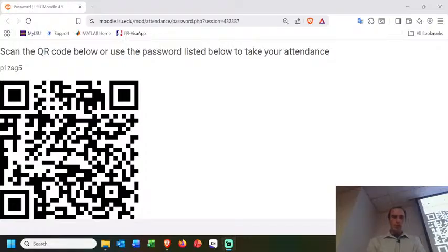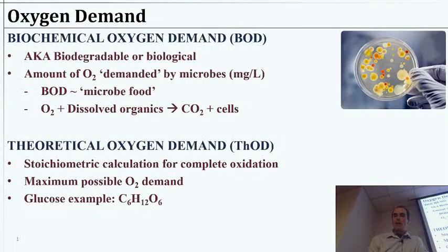And right now, today we're going to come back and talk about biological oxygen demand. So within the context of wastewater, we talked about this as kind of the primary conventional pollutant that we target because we don't want our rivers and waterways becoming anoxic because all the bacteria demand all the oxygen, right? We want to leave some oxygen for the fish. So we're going to come back and talk a little deeper about that with the plan of understanding how do we put some math to it? How do we know how much BOD is in the water? How do we do a test for that?